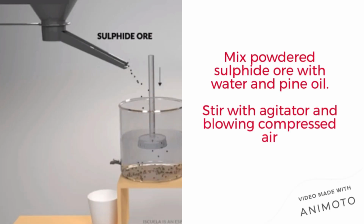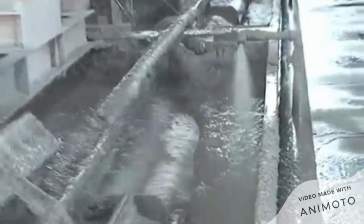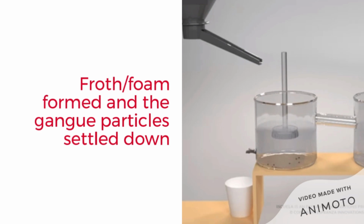Then the powdered ore is added and stirred vigorously with an agitator while blowing in compressed air. This results in the formation of the froth or foam. After the froth is formed and rises to the surface, the impurities or gangue particles are left to settle down in the tank.